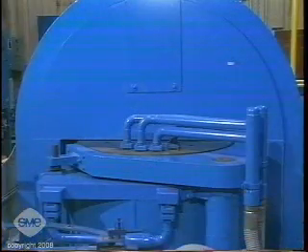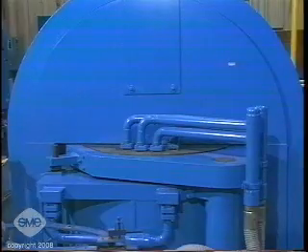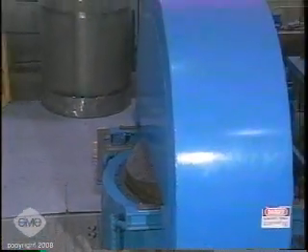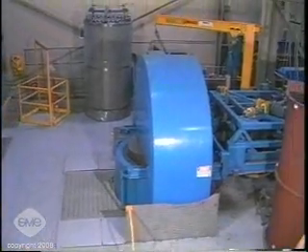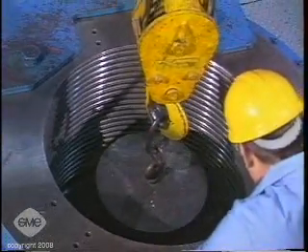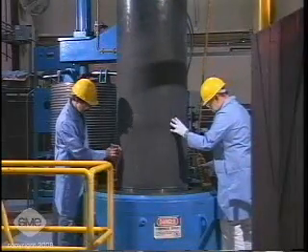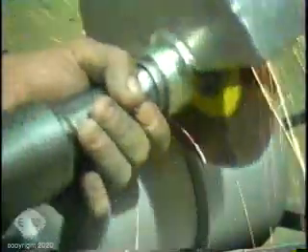Depending on the metal being processed, temperatures can range up to 2,500 degrees Fahrenheit, with pressures up to 45,000 psi or more. The gas, typically inert, is usually argon. Processing cycles are long, from several hours to more than a day. However, many parts can be processed simultaneously. After processing, the molds are removed by machining or chemical leaching.